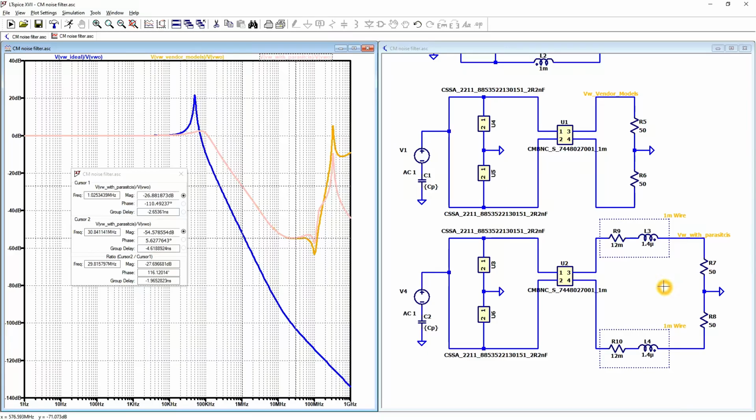And this will be all for the common mode simulation that we need to do. Our 1 millihenry common mode choke and two 2.2 nanofarad capacitors will be enough to damp the graph that we saw in the first part of this series. Let us see now how to design the differential mode noise part of the mains filter.